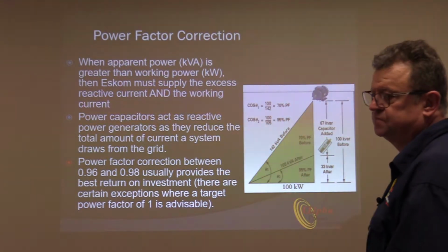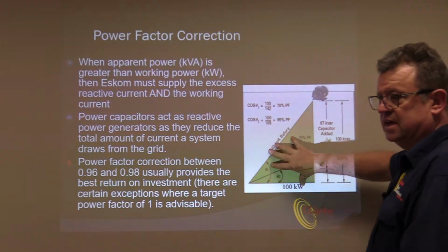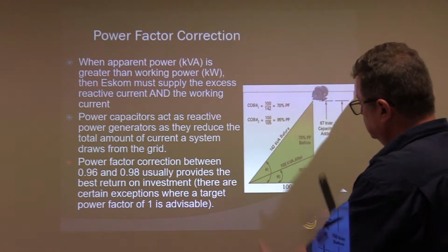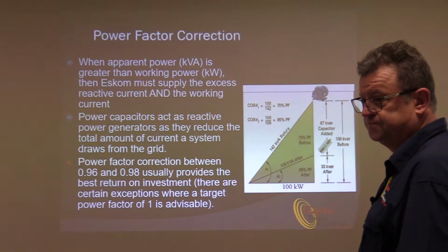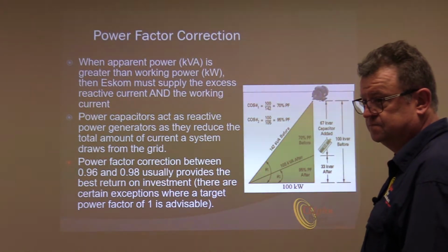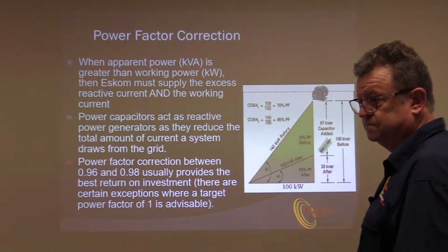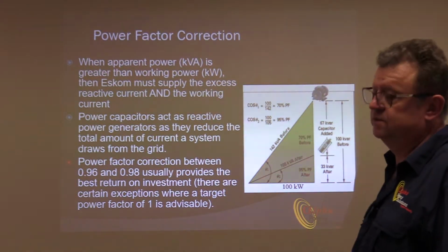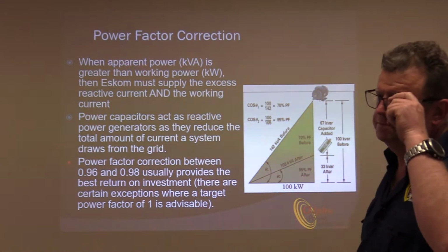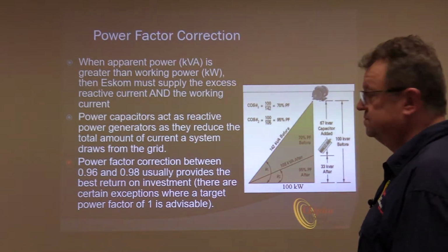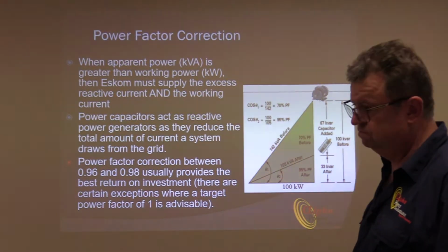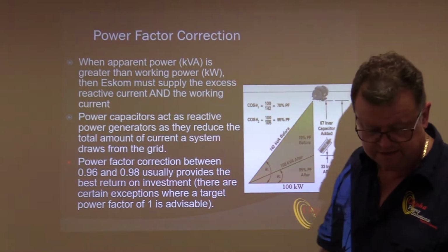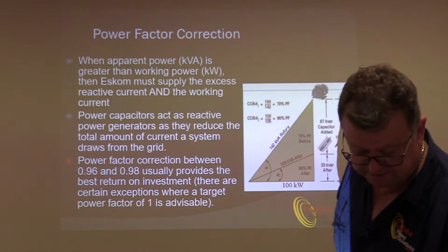Okay, that makes sense. Because this is not going to stay constant. As motors get switched on and off, or motors get more loaded or whatever, this is constantly changing. So it's important to have a power factor correction unit that can measure and implement steps automatically. They all do, no matter what make. Yeah, that's the minimum requirement. Okay, and they're all automatically selected. Absolutely. We'll come back to this triangle a bit later, because there's another issue that we need to explain.